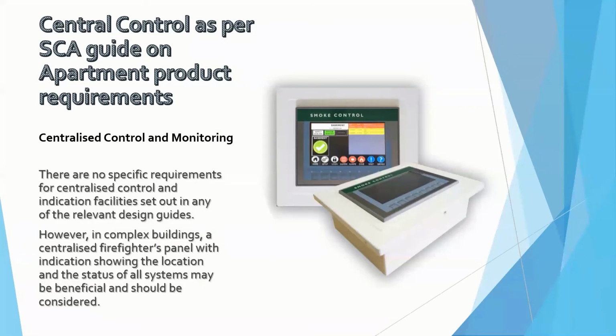Whilst there is no requirement for a firefighter's central control panel with monitoring facilities for residential buildings, in some complex projects, they may be useful in showing the fire services the system operational status. So we would also recommend this panel as being something to be added to a smoke control system.